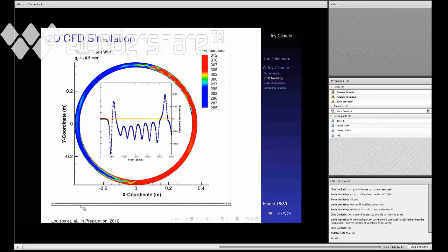We start the fluid off at a thermal equilibrium at 300 Kelvin. On the inset in the center here, what you're going to see is the bulk velocity of the fluid, which is the y variable of the Lorenz equations. And we're going to integrate that in time using the Navier-Stokes equations, which have something like 20 or 30,000 little mesh points in this annulus. And it's a full simulation of what goes on.